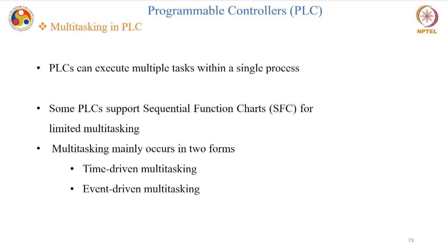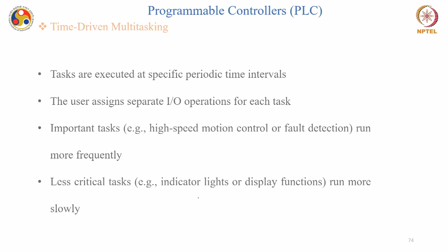So, you can understand this programmable logic controller, PLC, as a mini computer as well. Now, a PLC can execute multiple tasks within a single process. Some PLCs support sequential function chart, SFC, for limited multitasking. However, multitasking is always possible. Multitasking mainly occurs in two forms in a PLC: one is time driven multitasking, and we also have event driven multitasking.